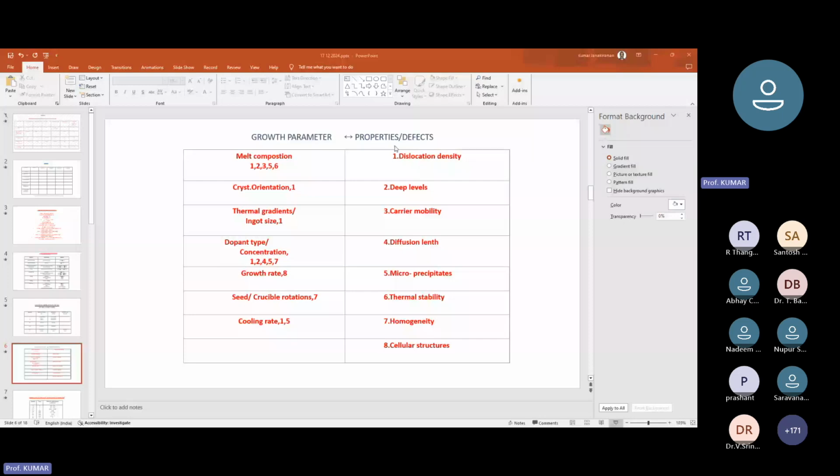You can use various heating elements like nichrome wire and other heating elements which are used in your iron boxes. There is a company famously by the name Kanthal. Kanthal produces various types of heating elements for resistive heating applications. There is a specialized heating element known as molybdenum disilicide, which is very good to use even in an open air environment.